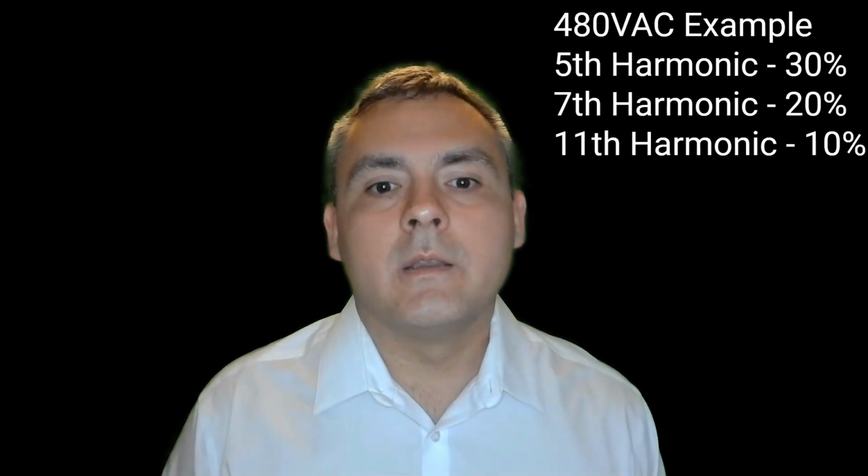Let's consider the same example we've been working on, but let's keep that fifth harmonic at 30%, the seventh at 20%, and the 11th at 10%. The K factor for this type of nonlinear harmonic loading would be 6.42. If I were specifying the transformer, then I would specify one at K factor 13 because that is the